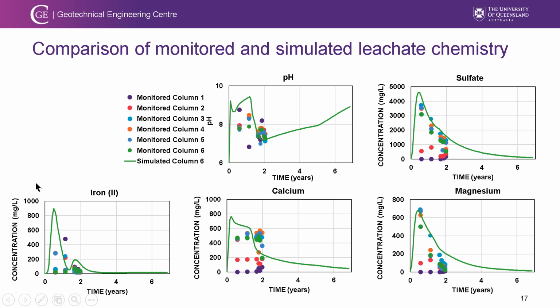The iron concentration shows a bit of an interesting result as compared to the sulfate. Remember that if it's pyrite oxidation, the amount of sulfate and iron needs to be proportional, but this is not the case because the iron concentration is relatively lower as compared to the sulfate concentration, which is probably induced by the iron precipitation within the column, which we'll discuss later on.